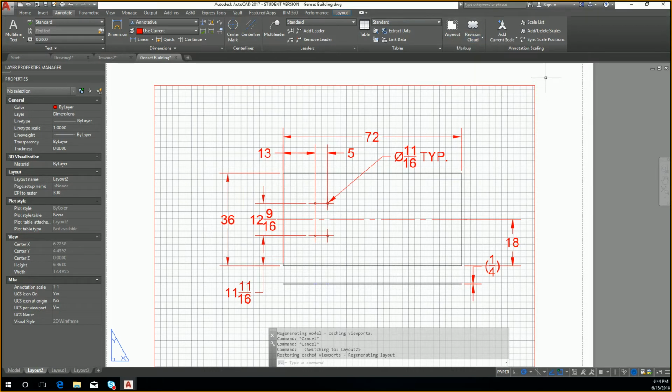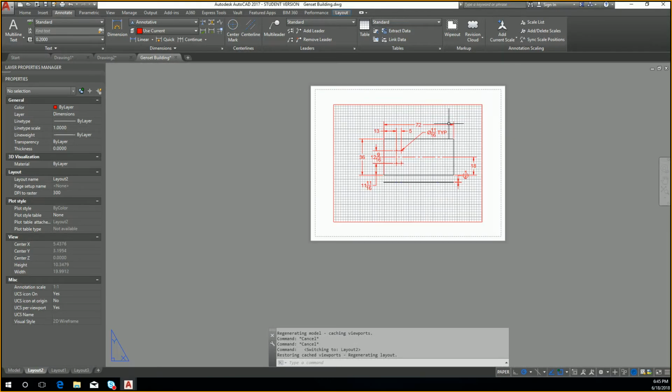All right, how many of you guys are familiar with the concept of revision drawings? So right now, everything that you are drawing in AutoCAD is your first draft, so to speak. So typically, companies will use either an alpha or a numeric way of numbering their versions. A lot of times, in good practice, you will have something that is a draft in a letter series simply for approvals. So what that means is you're going to be creating a drawing set, and typically in your title block,